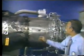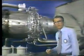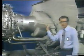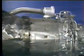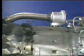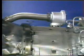The third supporting air system is the bleed air valve. Engine surge during startup and acceleration is prevented by the bleed air valve and variable vane system. During acceleration, an increasing pressure can build in the combustor which can stop the flow of air through the compressor. The bleed air valve, mounted on top of the combustor housing, bleeds this air pressure from the combustor to reduce the pressure and to prevent surge during acceleration.